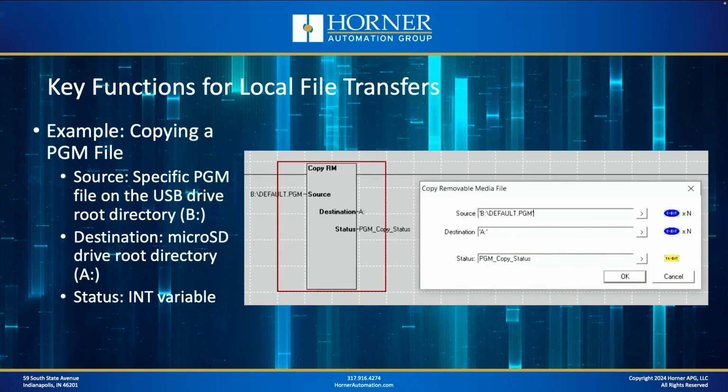Okay, so let's give a simple example here of copying a program file from the USB drive over to the microSD card. Now, you can load programs from the USB card. That is possible, but it's always good to have a copy of the microSD card inside the main microSD drive of the controller, and a lot of times you really want to load it from that drive anyway. The microSD cards typically are more reliable, and of course, if they're not accessible from the outside of the panel, they're more likely to actually be in there.